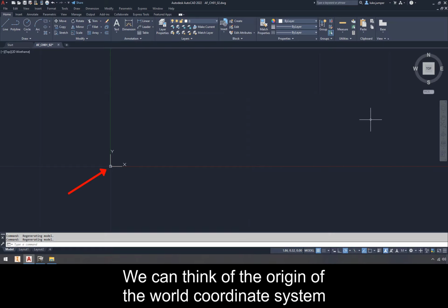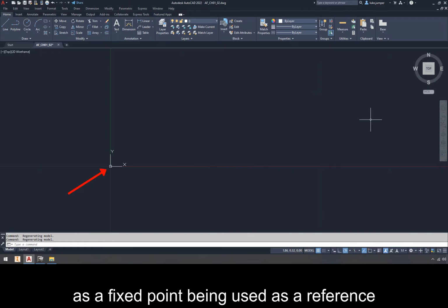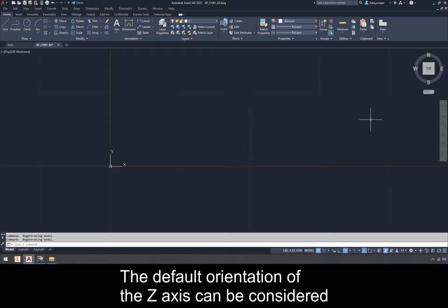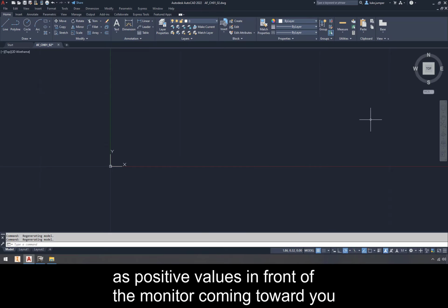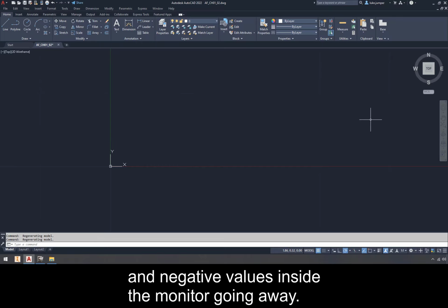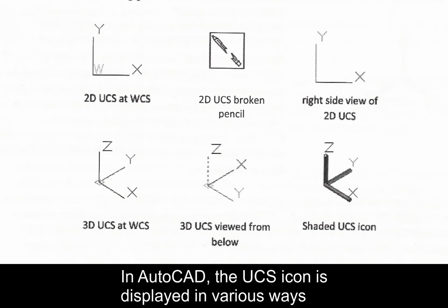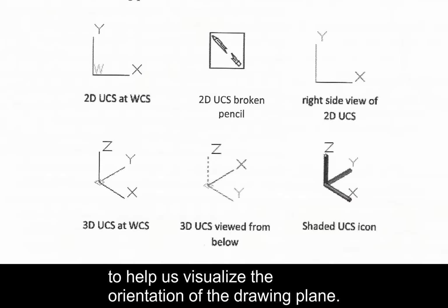We can think of the origin of the world coordinate system as a fixed point being used as a reference for all measurements. The default orientation of the z-axis can be considered as positive values in front of the monitor, coming towards you, and negative values inside the monitor, going away. Sometimes you'll notice changes to the 2D UCS icon display. In AutoCAD, the UCS icon is displayed in various ways to help us visualize the orientation of the drawing plane.